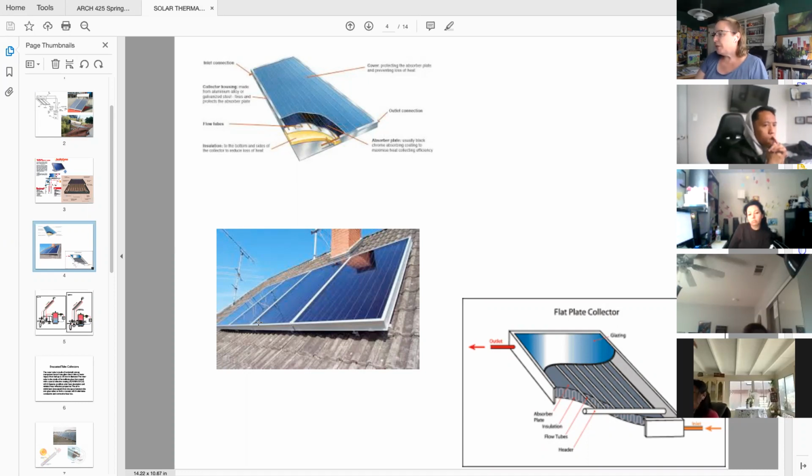For multifamily houses, a lot of low income projects install solar hot water systems because they get huge operational cost savings on their gas bills. And now that the state's moving forward to eliminating natural gas, it's even that much more efficient to pair a solar hot water heating system with a very small electrical backup heater or a heat pump. Remember, electrical hot water heating is not very efficient.